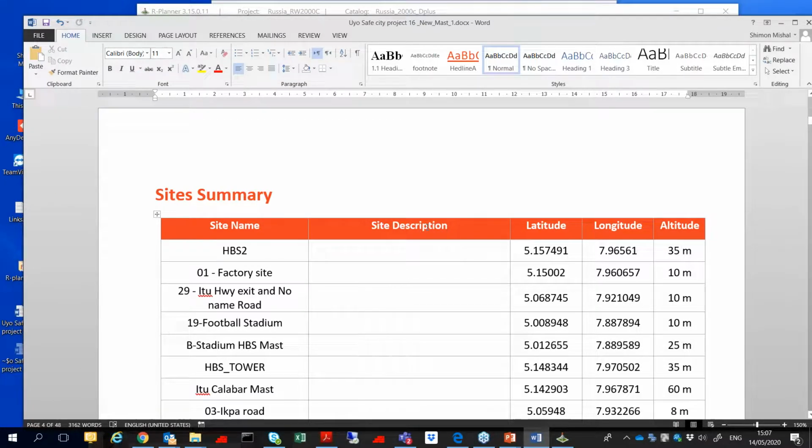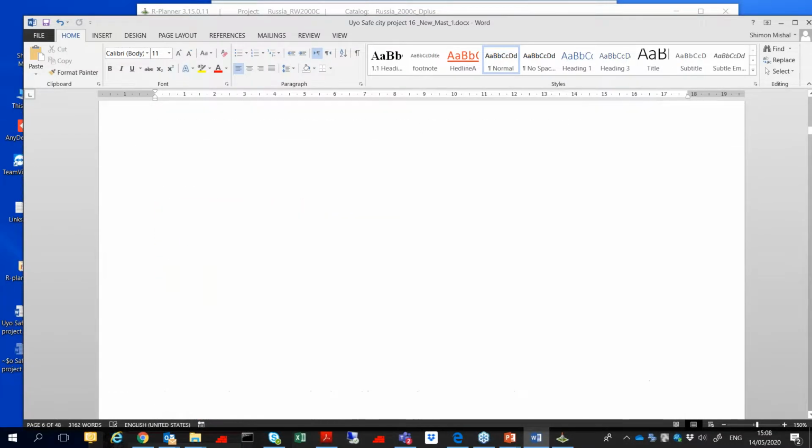And later on, when the installer or system integrator is going to the site, we need to implement those sites, looking for the transmission, looking at the power, if there are enough transmission point connections, if there is enough power, lightning protectors, POEs, grounding. All this stuff needs to be taken into consideration in the BOM. And this is the report.